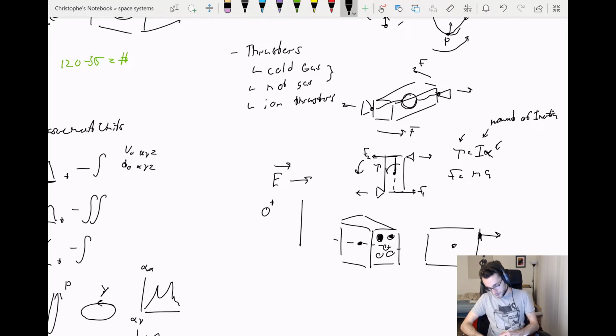they have a force, so they're flinging things out the back, they're giving you a force in this direction. What you can do is, hey, that is a little radius, and that's some force. I'm actually imparting a moment on the spacecraft because it's giving off-axis thrust. So if you want to change your attitude ever so slightly, if you have ion engines or something like that, you can change your attitude a little bit.